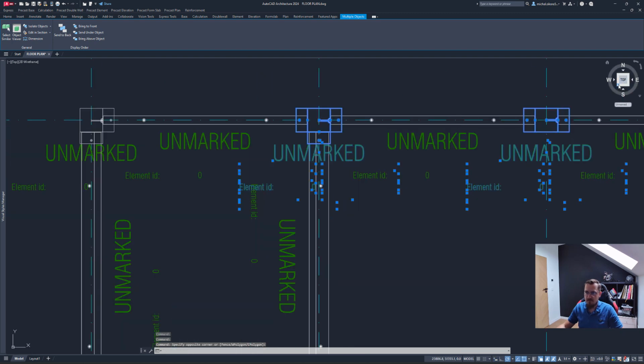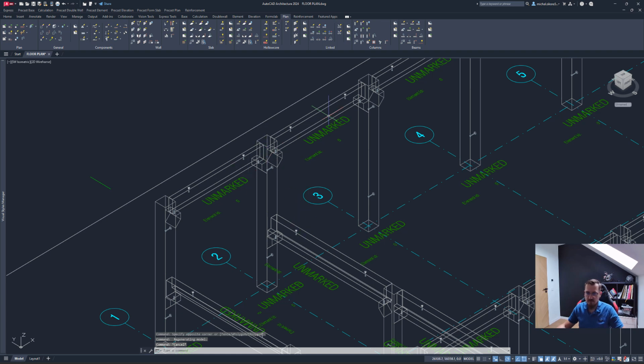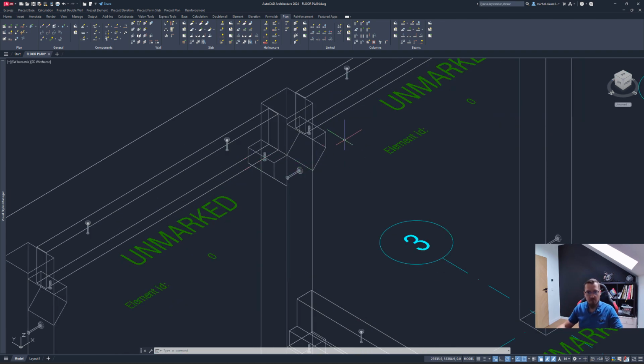As you can see, the corbels have been added to the columns, like so, and it doesn't even matter for the software that those beams are at two different levels and going in different directions. It basically recognizes, okay, this column has beams here and here, I need to support those, and there's a beam here on the lower level as well, let's support that beam as well. So here it is, that's done. The reinforcement of the corbel, we'll be doing that later at the drawing stage actually.